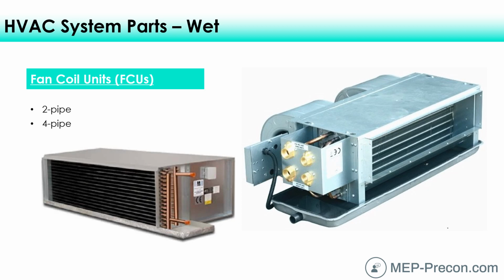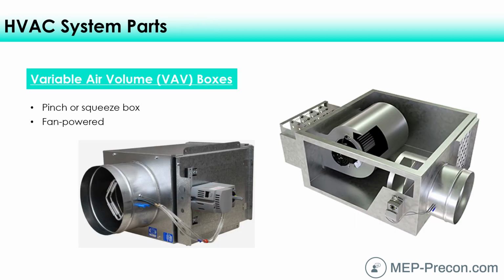All right, we've talked about fan coils adequately here. Let's just talk about one more part of a system. A popular system, you may have heard, is what's called a variable air volume system. A variable air volume system has a big air handler, of the slides that we saw, 10 slides or so, and that would deliver air out to these what are called variable air volume boxes.